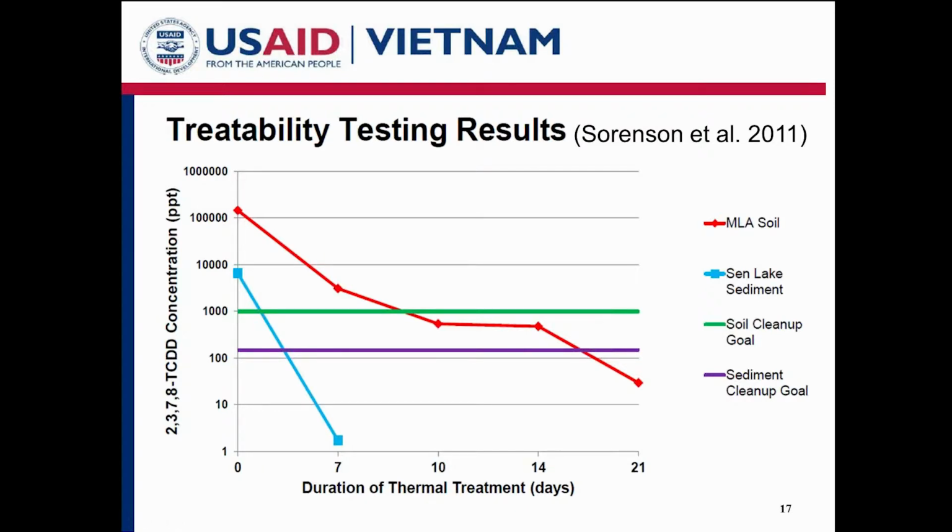And for those of you who may be more familiar with incineration of soil and wondering why a temperature of 335 C could be sufficient, it's really this long residence time at temperature that makes the difference. With incineration, it's typical that a packet of soil is only heated to the target temperature for seconds or at most maybe a minute. And here we're able to heat and stay at temperature for days or weeks.